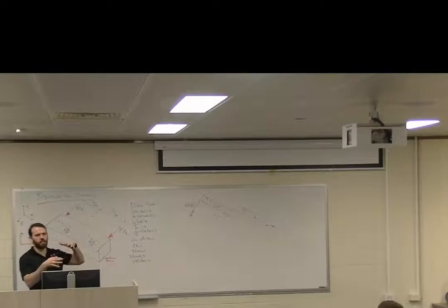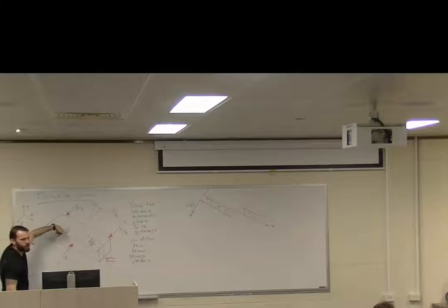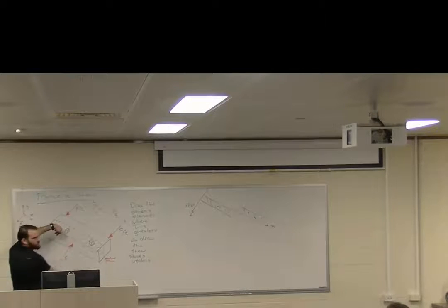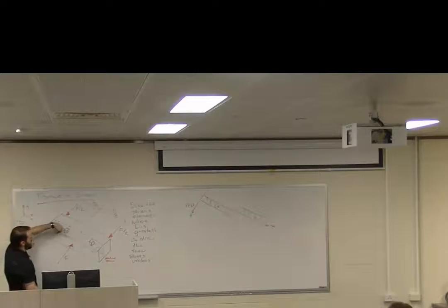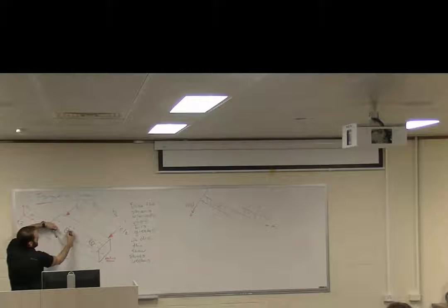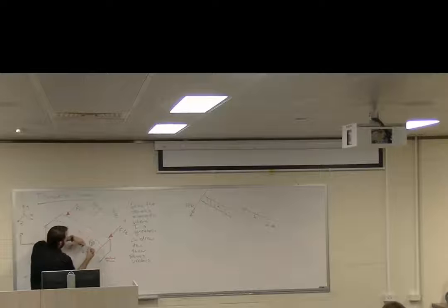In your mind, hopefully you don't need to draw it, you can look at your shear force diagram and use your hands in the air if you need to, lay it down flat, that matches that, and think about positives and negatives. Remembering that Z positive is that way, so our positive sign convention needs to be oriented the same way. So if that's up, then a positive shear would be down, right? And a negative shear would be up.